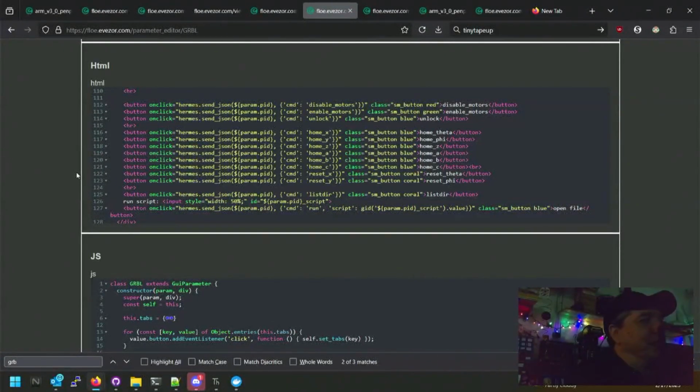it's locked at 115K, right? No, it's not. You can change it. Oh, I thought. Is this new? No, it's with the channels. You can set the baud rate to whatever you want, so things like FluidNC and web UI and stuff like that. Also, the debugging, like backtrace, is all done at 115 by default, and when the chip starts up, so you might as well just stick with that.